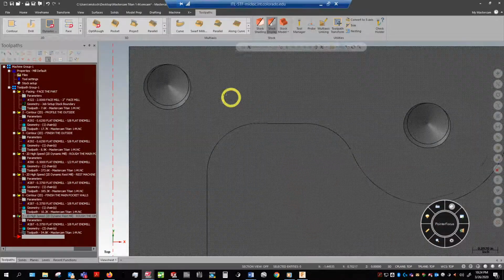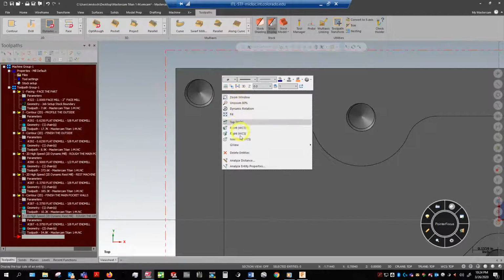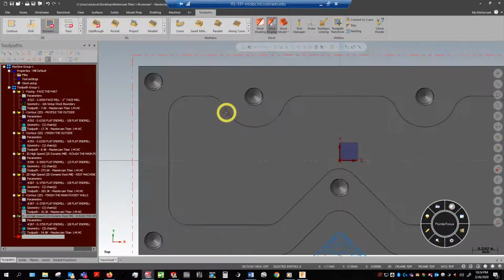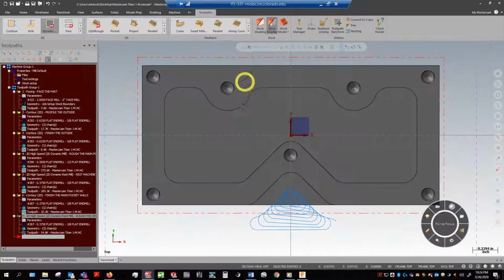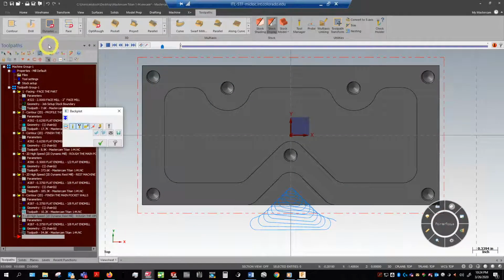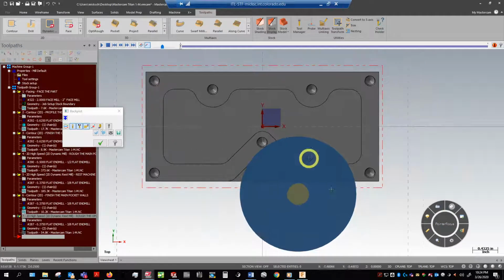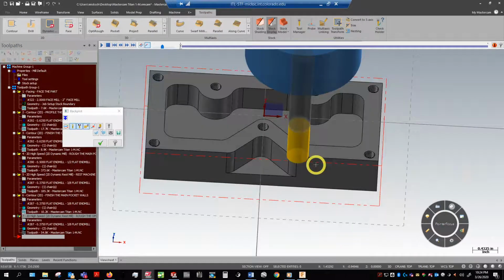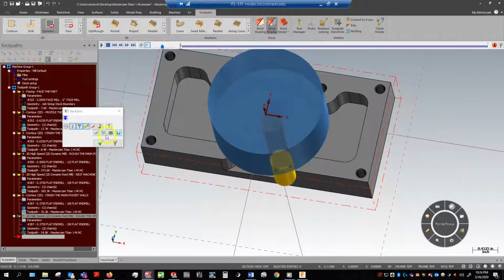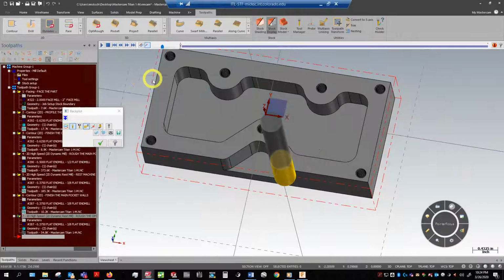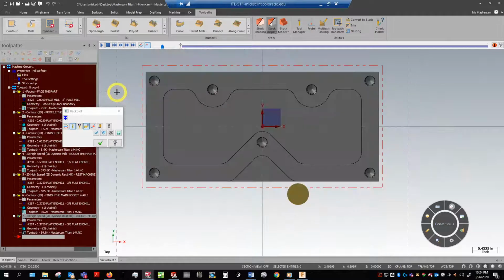There we go. Fit this to my screen here. As you can see, it's a pretty good looking toolpath, so let's backplot that and play through it. Once again, my mouse clicks are not showing up. I can see that tool holder, and it's kind of bothersome when I'm looking at it from a top-down view, so why don't we turn that off? We can click this icon, display the holder, turn that off, go back into a top view, and see what this toolpath is going to do.